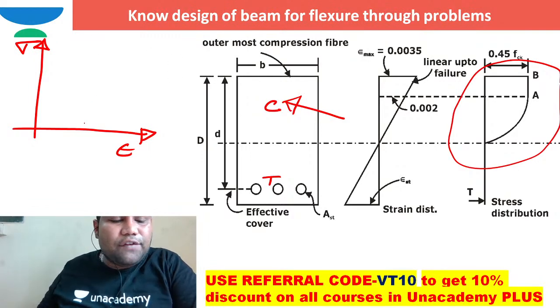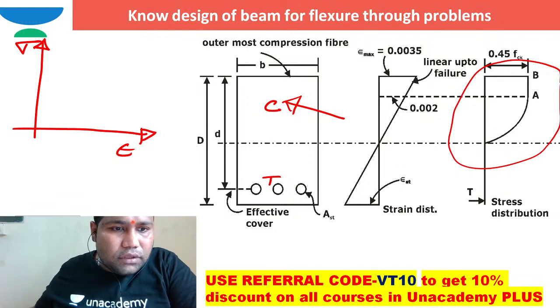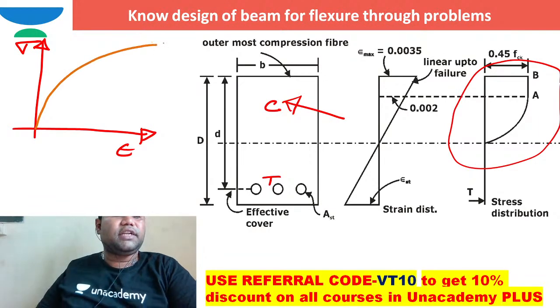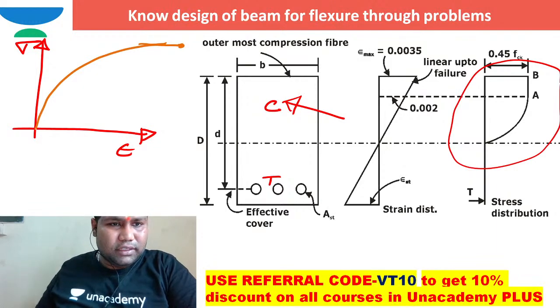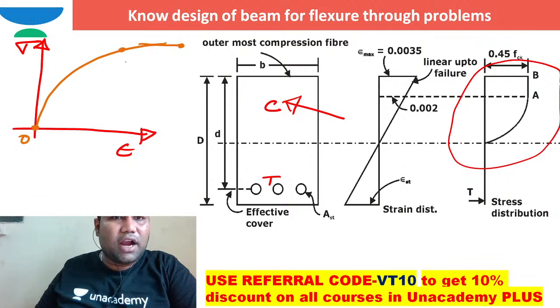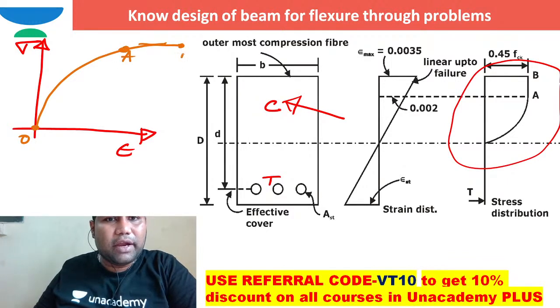I hope you can take a concrete cube, and if you are testing it for axial compression, this is how the shape of the stress strain curve is possible. This is stress and this is strain, and it will come in a parabolic way like this, definitely. This is how the stress strain curve looks, and somewhere it will fail here. Let me say this is origin O, this point is called A, and this point is called B.